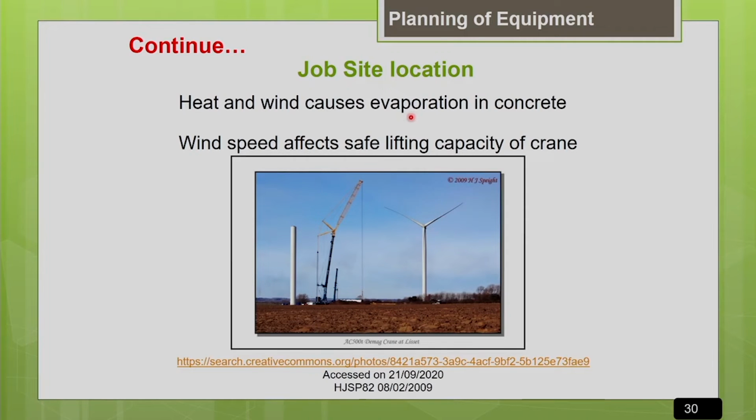So in those places, you should have some facility to protect the concrete during the making of concrete, and even after the concrete is made, it should be properly protected from severe weather conditions. And you should start the curing of concrete as early as possible in aggressive conditions to protect the concrete from cracking.